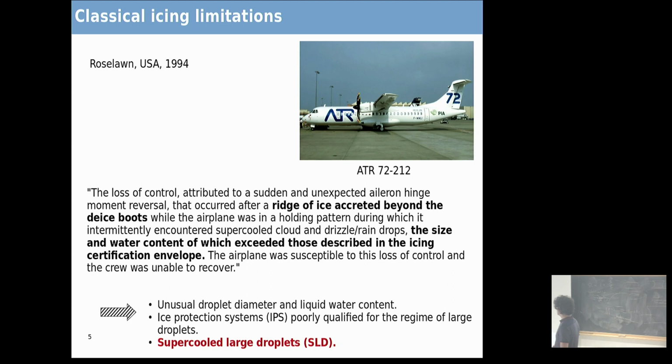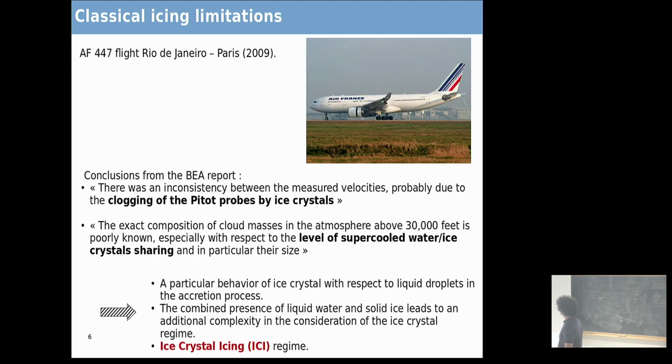So, as a conclusion, there are now unusual droplet diameters and liquid water contents that had never been expected to happen. The problem is that the ice protection systems, which have been developed for classical icing, are poorly qualified for the regime of SLD, and that just justifies the SLD work.